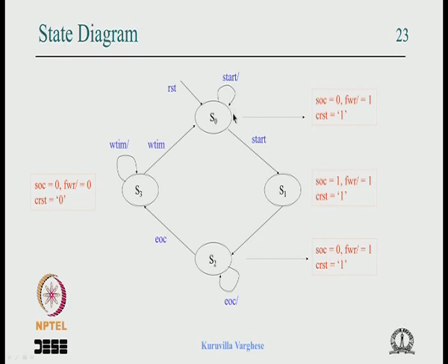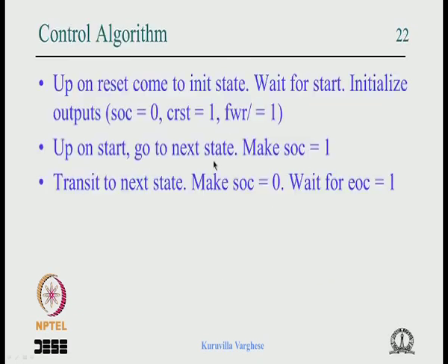One thing you see is that we are looking at the start signal only at this state. It is a very good thing, because the logic becomes simple. If you looked at the start signal in every state, the next state logic would become complex. But it has a beautiful advantage: once we start the conversion process, even if start goes low in between, we do not care, whatever was started is completed. Sometimes keeping things simple results in a very elegant solution, as is evident in the timing diagram.